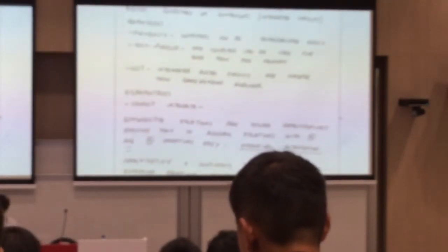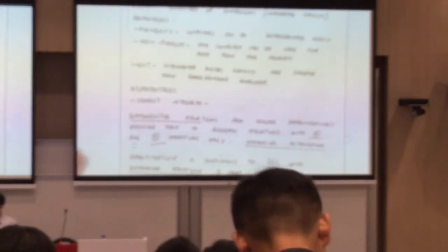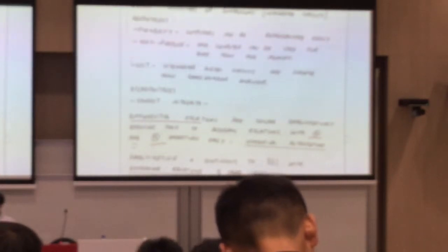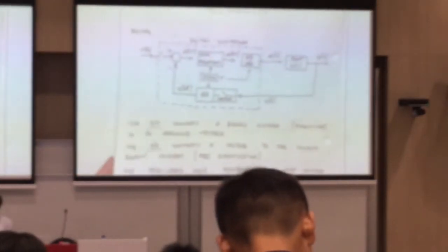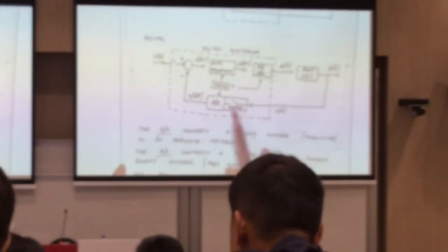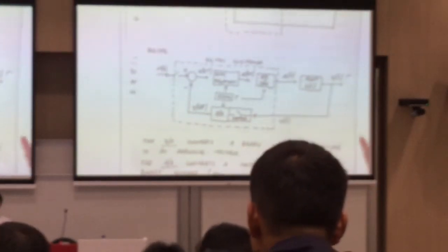So for the digital controller, instead of differential equations, we are going to do difference equations, with plus and multiplication. We are going to do something called numeric integration, which is basically summing up the integration. So here we present what I said: basically you have three parts. Analog to digital, differential equation to difference equation, and then digital to analog converter.